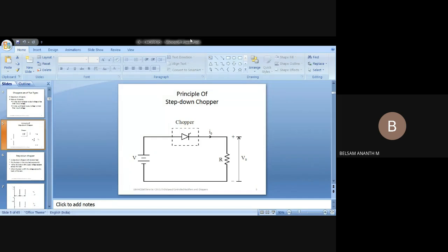Well, I hope you remember there is a type 0 system with order 1, which maybe in the fourth semester you learned. If I have a chopper or a thyristor in the system, with the voltage source and the resistance, then what is my output current value? I equals V by R into 1 minus e power minus R by L into T. That is what you discussed in the time domain analysis, the steady state analysis on the order and system of your dynamics. I hope you learned, right?